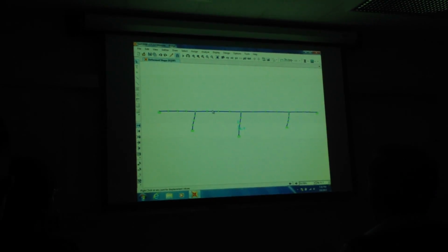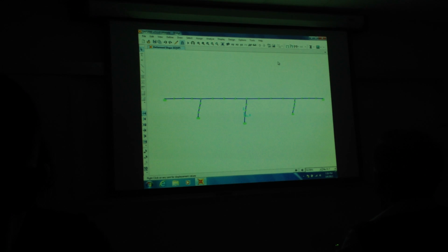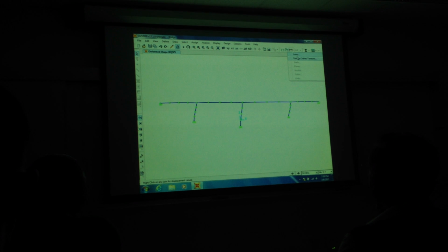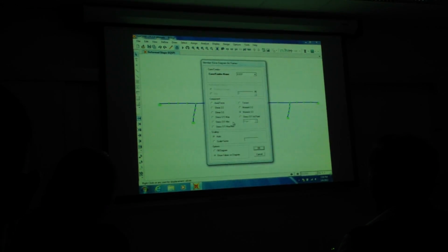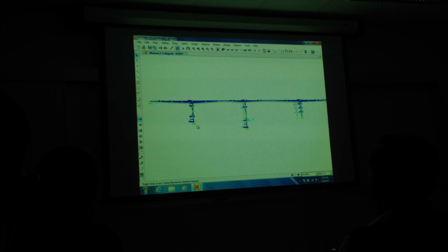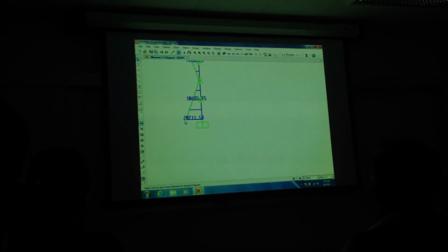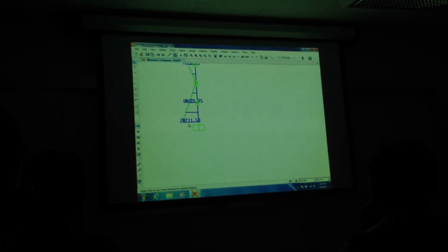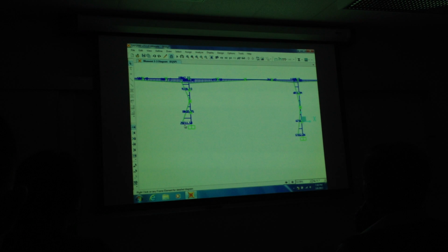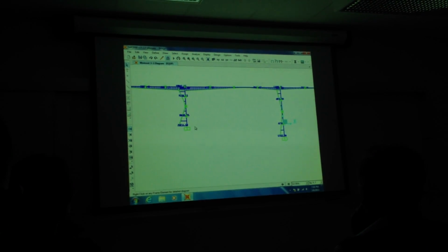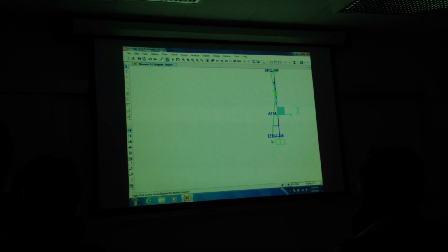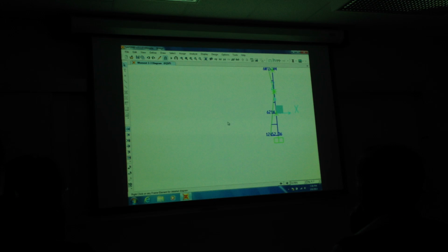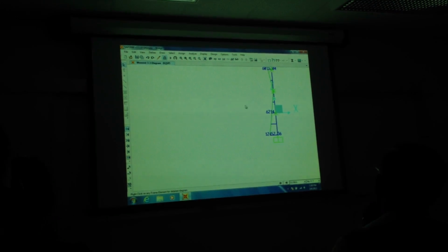Let's look at a moment. We don't have to plot a time history, we just pull off the maximum results, so we can say, show us the moment 3-3, that's it. Zoom in, and look, 20,700. Is that similar? From the earthquake time history, the maximum was 20,000 something, right? Over here, we see 12,000. So there's the response spectrum approach, the time history approach. Now when things go nonlinear, you need to go to time history.